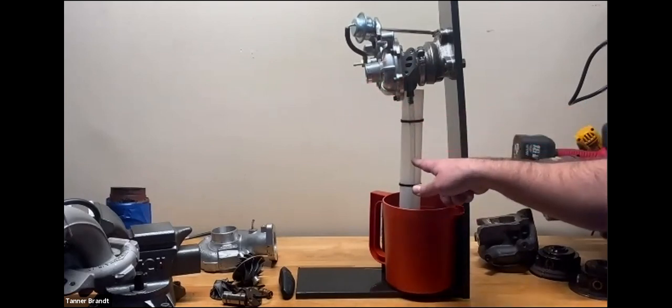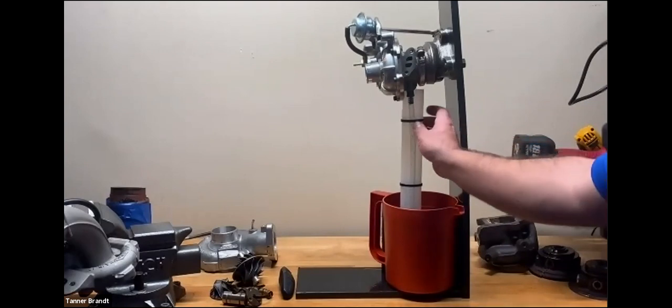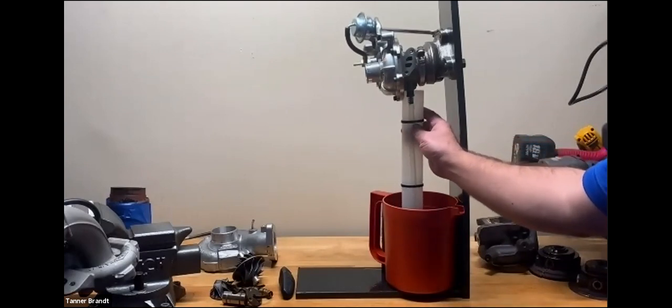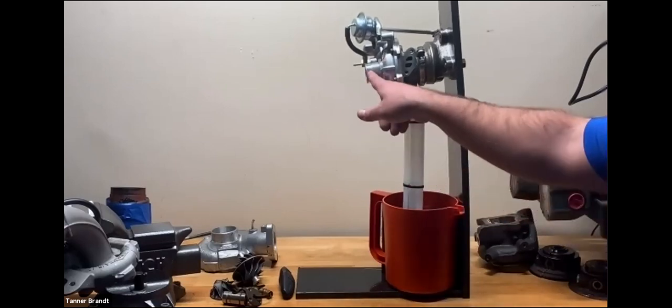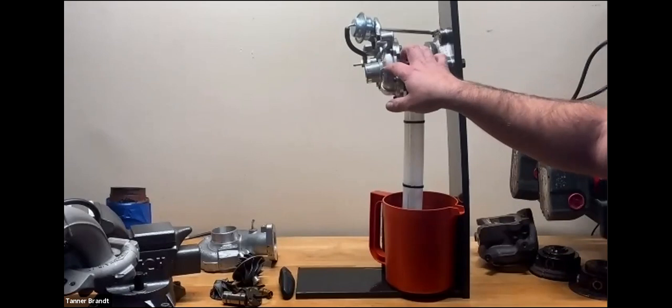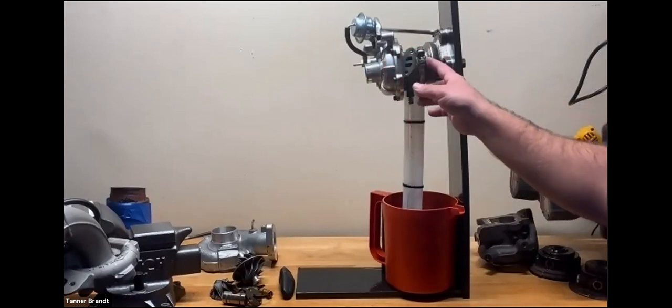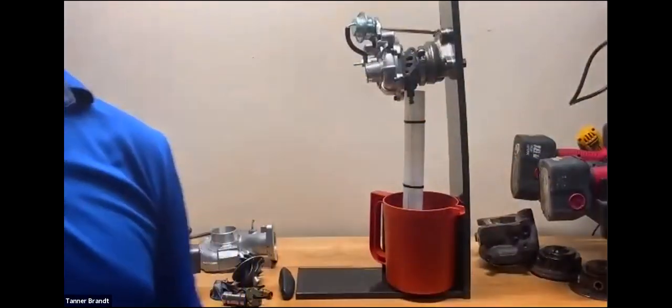There's going to be oil that's going to be flowing down through this. And when there's oil flowing down through that, it's going to be full. So if a vacuum is applied to this side of it, since we know that there's not an actual hard seal in it, it's going to be able to pull vacuum into the bearing housing. And we'll look and see what happens.